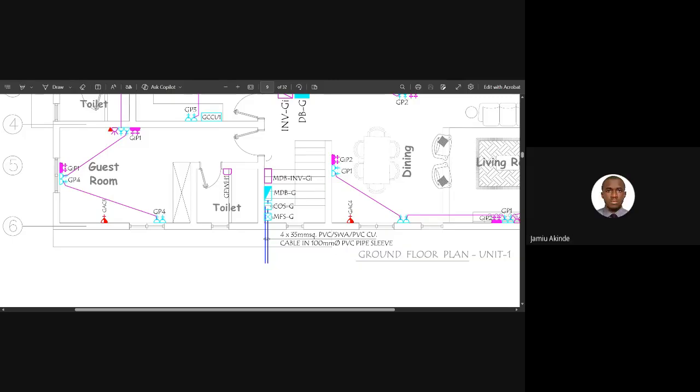I'm with you, sir. Now, you know that we say the height of our pole is what? How many meters? 12 meters. Now, write 12 meters, height of the pole. Now, you know that I said we will allow for 2 meters for what? Termination. Write 2 meters, termination of cable to the high tension. Yes or no?